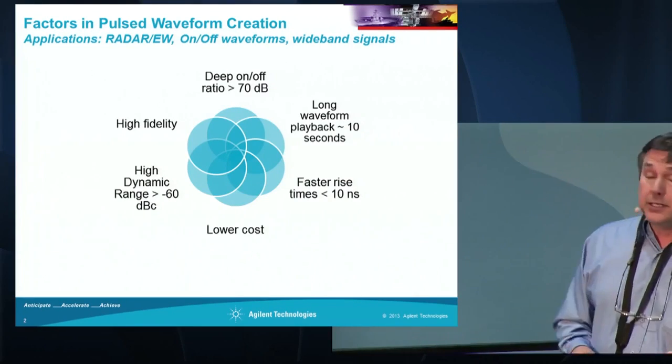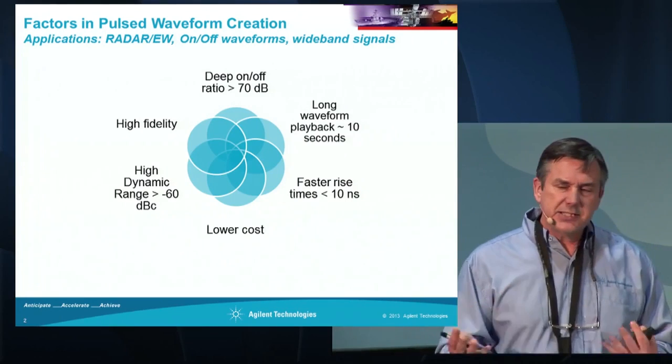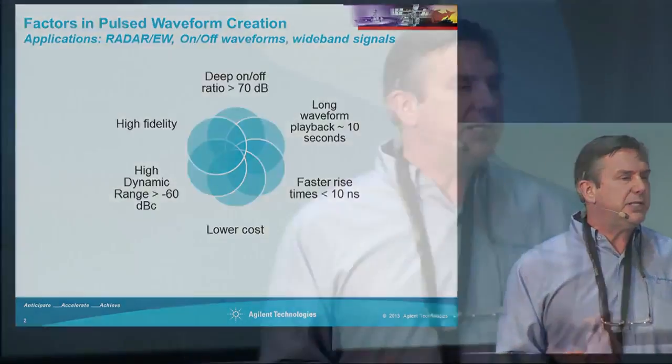Long playback, of course, that's required for a lot of different waveforms, but in radar it's specifically needed because the signals aren't necessarily repeating. A lot of times we work with pulse waveforms that are just repeating the same thing over and over again, but that's rarely the use case. The use case is going to be a flight of a radar-guided missile, where the return signal and the transmitted signal are getting closer together. The distortions that are seen are going to be varying with time at a very slow rate.